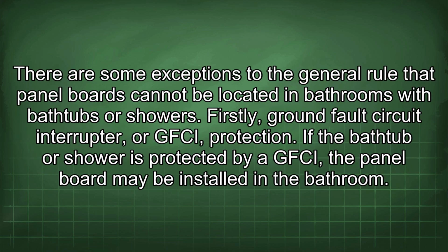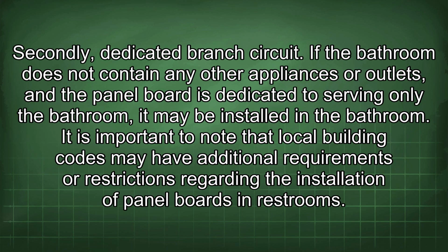There are some exceptions to the general rule that panel boards cannot be located in bathrooms with bathtubs or showers. Firstly, ground fault circuit interrupter, or GFCI, protection. If the bathtub or shower is protected by a GFCI, the panel board may be installed in the bathroom. Secondly, dedicated branch circuit. If the bathroom does not contain any other appliances or outlets, and the panel board is dedicated to serving only the bathroom, it may be installed in the bathroom.